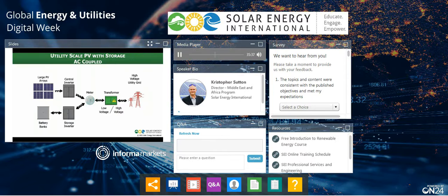Now, one thing that we're seeing happening with big solar farms, big power plants, is the ability to connect batteries in there with it. As we get into larger and larger amounts of solar in the world on big utility grids, the higher what we call grid penetration, the amount of solar as a percentage to the size of the grid, we can get enough energy that fluctuations in sun and clouds can really start to push the grid around a little bit with big solar farms.